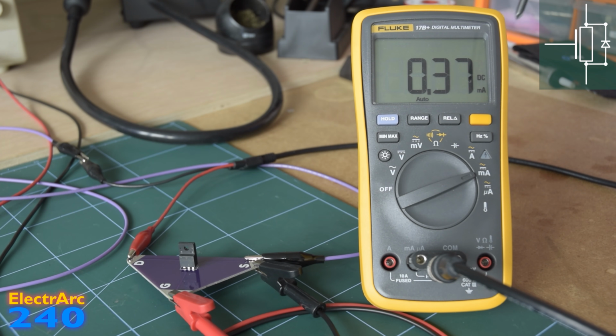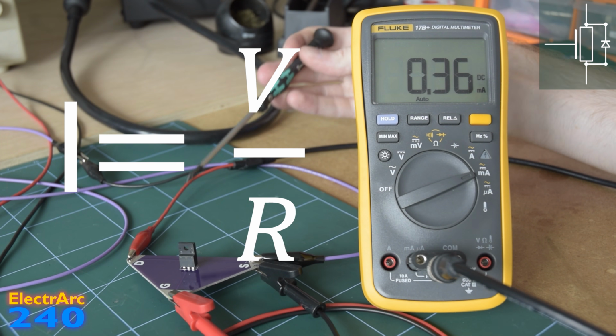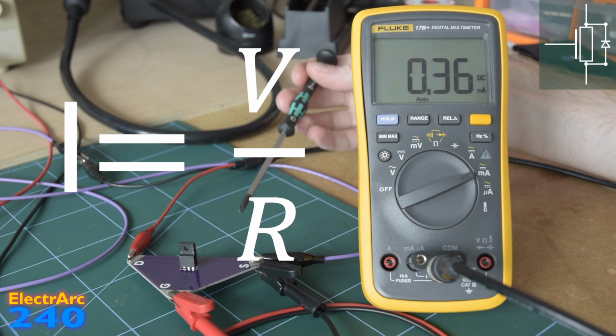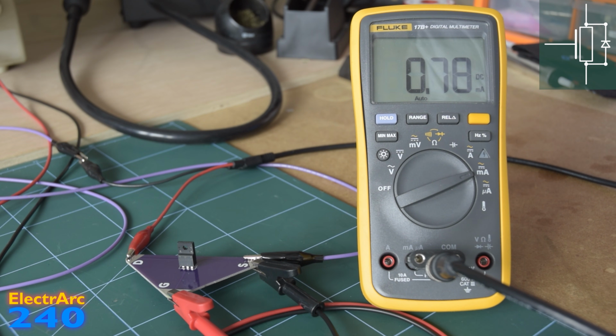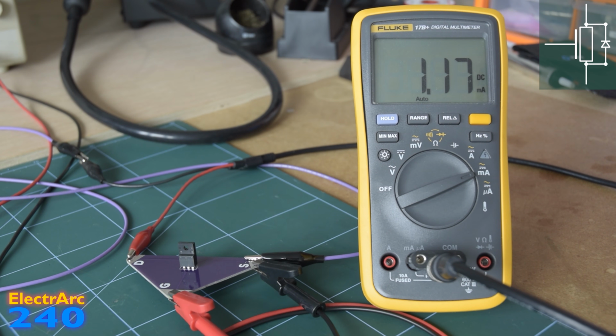The current flowing is equal to the voltage I'm applying divided by the on resistance for this specific gate source voltage. If I continue to increase the drain source voltage, we'll see that quite quickly the current stops increasing. So I'm at 1 volt, 3 volts, 6 volts, 10 volts, 15 volts, and right the way up to 30 volts, where you can see we still haven't really gone that far over 1 milliamp. So that's the saturation current for this gate source voltage, about 3 volts.